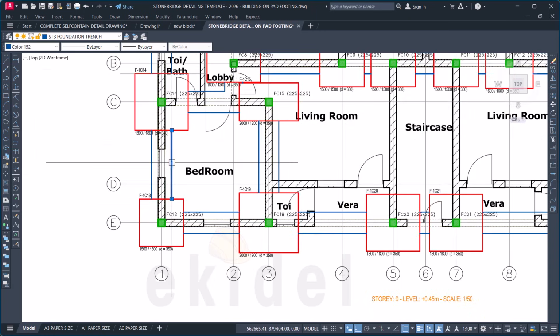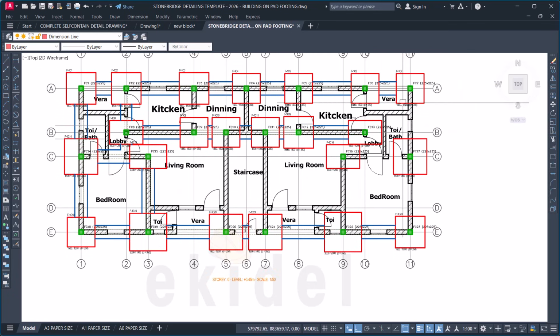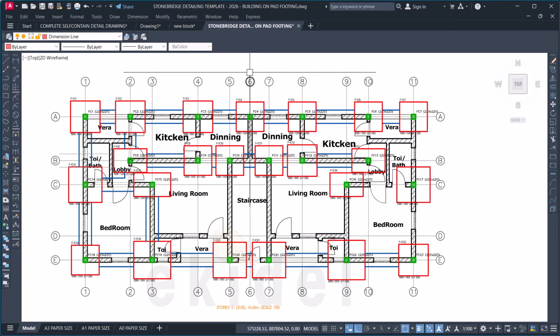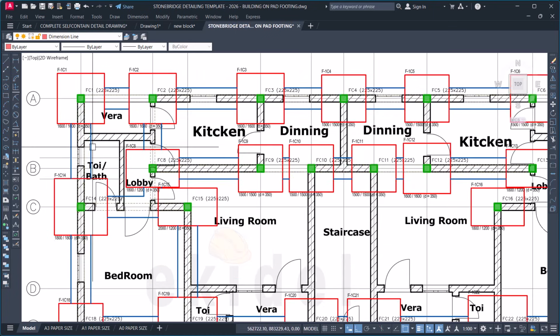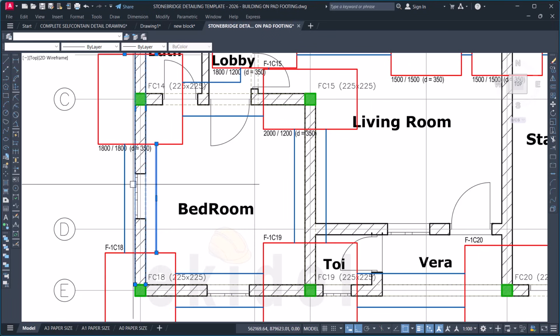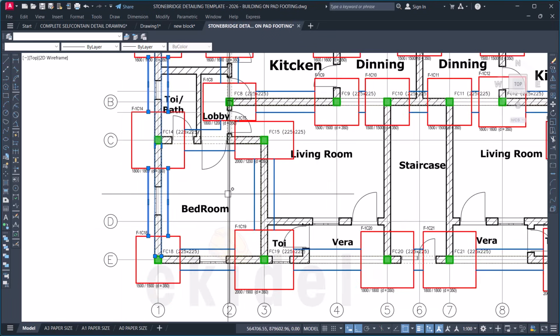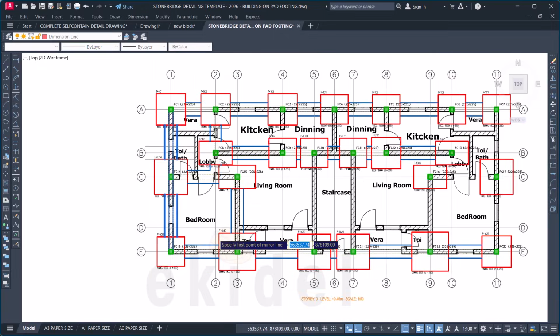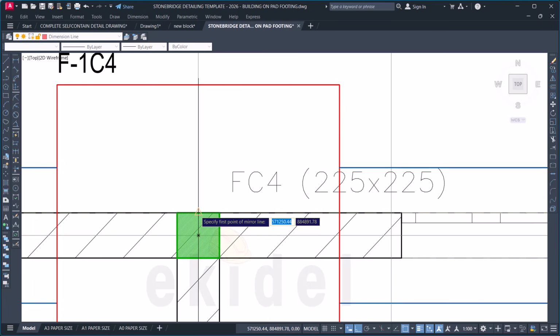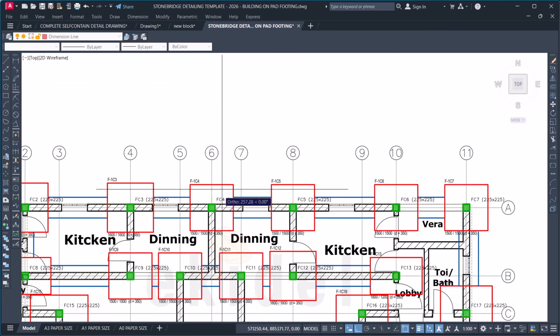I can choose to also copy this now. Now I can see again, this is a flip. So I can choose to flip this later by using a point here. This is our grid line 6, our central line to flip. For example, I can choose to click here, and then click here, okay, and again click here, and I'll choose mirror. I'll now say MI, which is mirror. I can choose to mirror it from this grid line 6, which is the center point here. That is if you have a similar thing with yours. Else you do it manually.